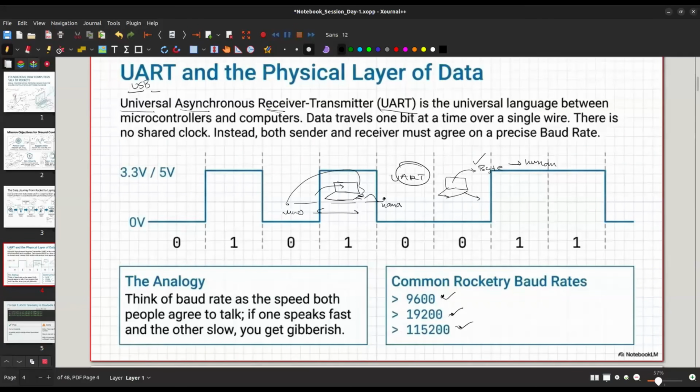Try to go up, it depends on how fast you want the communication to be understood and how fast your GCS is capable of decoding it. So when I was on the mission, building a GCS, 115200 was the baud rate that I used to decode it.